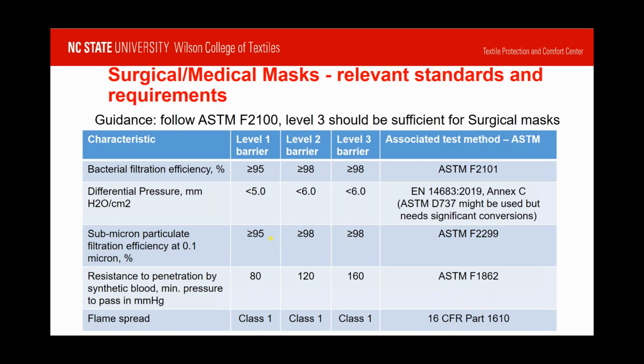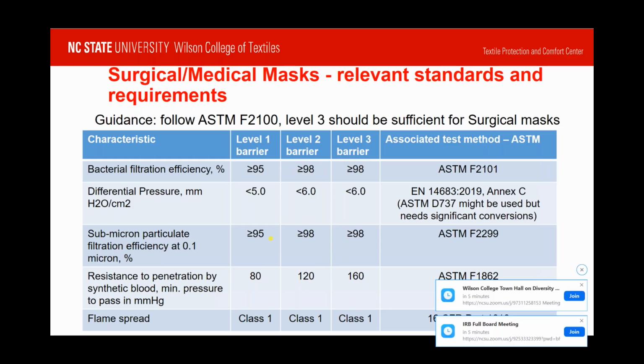But those two, the diffusion Brownian motion process, which is more effective for very small particles, and the capturing sieving effect of filters, and I hope Steve is not going to punish me for that one, for the larger particles, both of them have a minimum around 0.3 micron. And yeah, let's leave it at that for now.